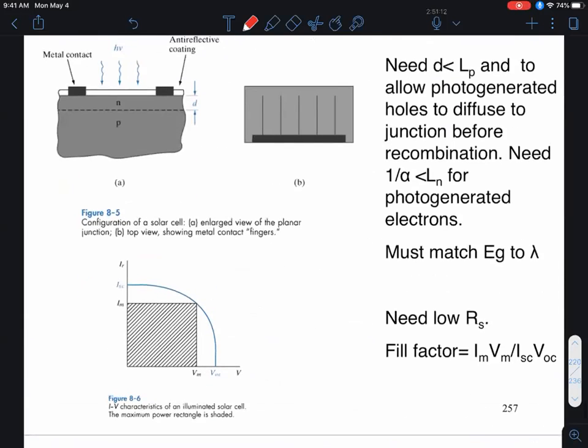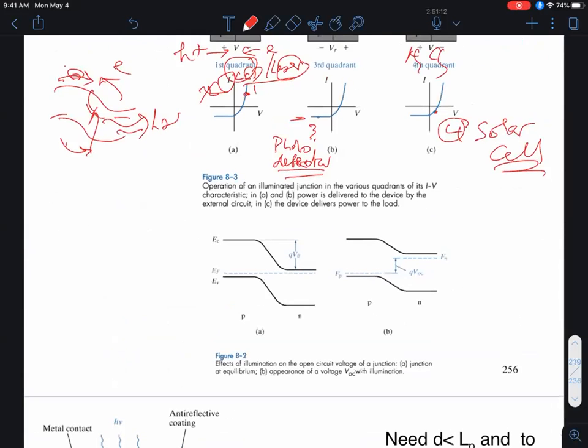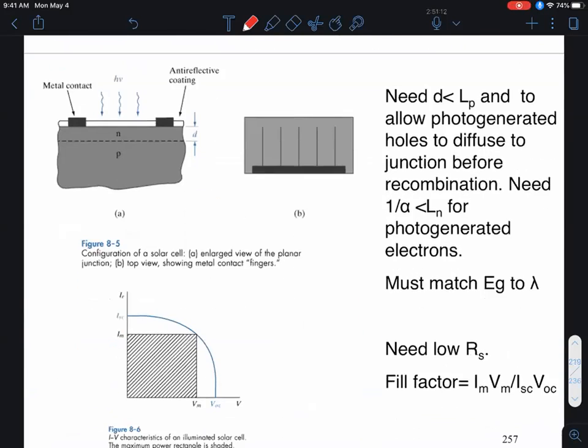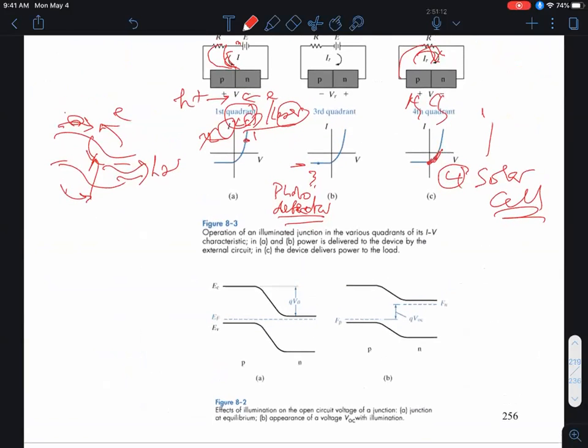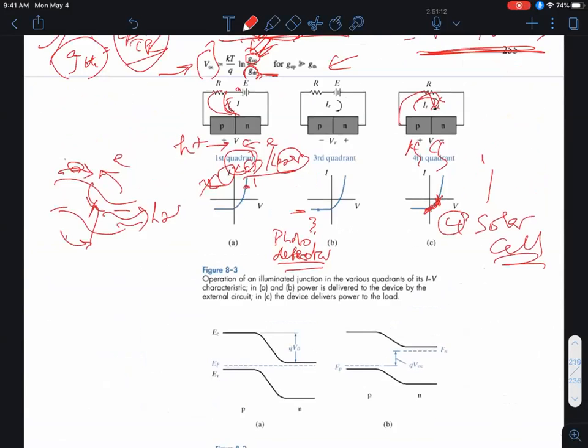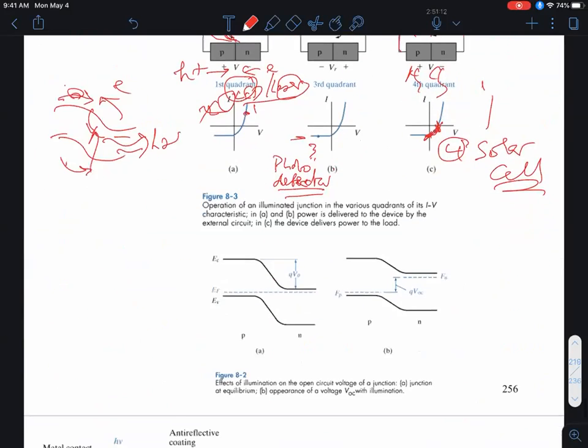Okay, but before I go to that, this is the solar cell IV, but here in the IV, I have flipped the figure, I made it upside down. So the solar cell IV is this part. In the next slide, I flip it by 180 degrees. So this curve looks inverted like this, okay? So when I go to that, don't get confused by this IV. All right, so for this solar cell, the two important parameters are the short circuit current and the open circuit voltage that I derived in the previous figure, all right?